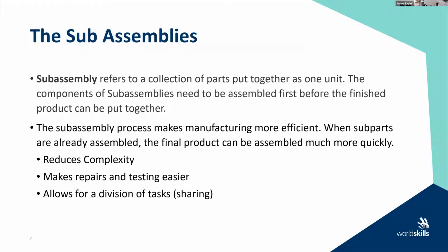For your World Skills team members, that can be one team member working on that, or one part of a team if you have more of a team supporting you. We then take the rest of the assemblies and break those down into sub-assemblies, right? This also makes repairs easier, because we'll build separate extra small sub-assemblies, so that if we break a shaft or a motor or a belt or something, we don't have to replace the one part. We just quickly take the sub-assembly off and put the new previously tested sub-assembly back onto the robot, right? So you want to make sure you have spares.